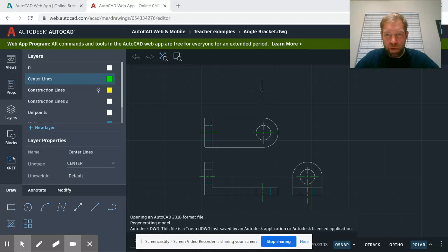I want to continue on with what we talked about last Thursday and Friday in class, and we focused on what you're looking at here. This is known as orthographic projection, or basically three views. So you have a top view, a front view, and a side view of a three-dimensional object, but it's shown in two dimensions. This class is two-dimensional drafting, and we can draw it in a way that still represents what the three-dimensional object would look like, but using two dimensions.